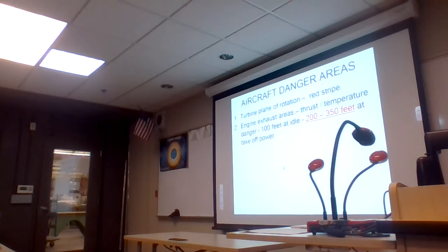Engine exhaust areas, again, an FAA test question will ask about this, so I've got it in red. Again, the exhaust areas at full power, anywhere from 200 to 350 feet, are really the area you want to avoid. Engine intake areas are always a foreign object damage area within a distance of about 25 feet or so. There's potential of swallowing something into the engine inlet. So again, kind of important.